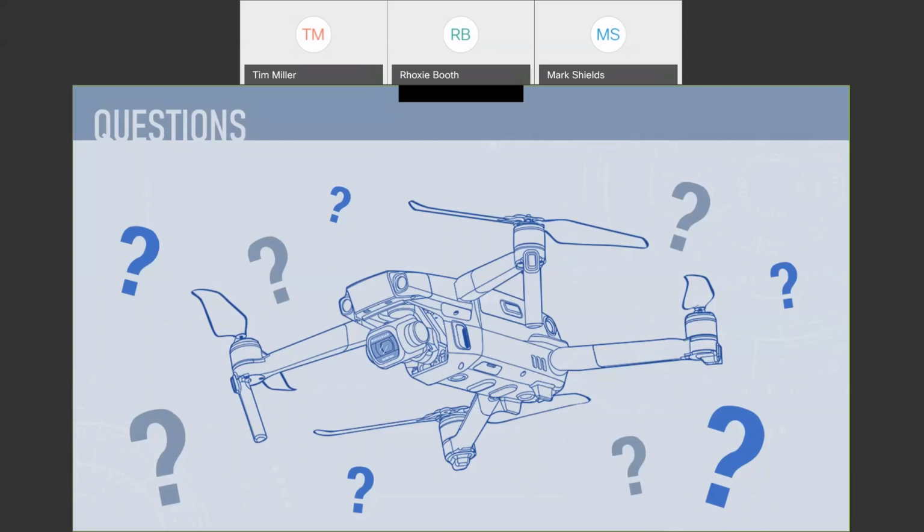And then another question: if you're not supposed to fly over people, how difficult is it to fly over to observe schools? Well, that's another good question. That's one of the waivers that you can actually get from the FAA. If you're flying in restricted airspace, it's usually an instantaneous yes or no. But with things like this, you would have to submit a waiver 90 days before the mission, and then you would get permission to do so. In a situation with a school, the school counts, they were stationary. They were sitting in the air in one spot the entire time, and that spot was roped off. Nobody can walk directly under the drone. That's the interesting thing, specifically with tethered drones. You put them in the air, they stay right there.